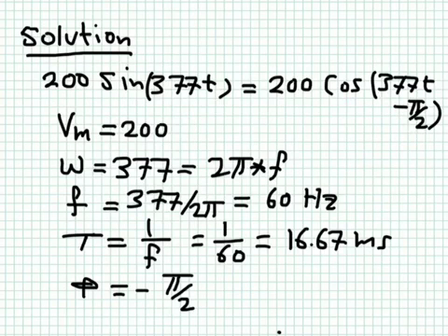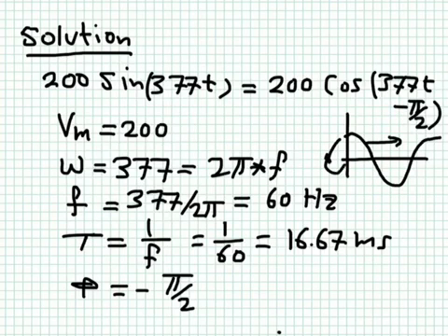This has to be very clear in your minds, because you're going to be using this over and over again. This is a cosine signal. If I shift it this way by just pi over 2, so that I bring this point here, this becomes a sine. This is why any sine is a cosine minus a phase shift of pi over 2. And notice that when I shift the signal in the positive t direction, I subtract from the phase. I don't add to the phase. Many people get confused about that, but this is how the formulation for sinusoidal signals goes.